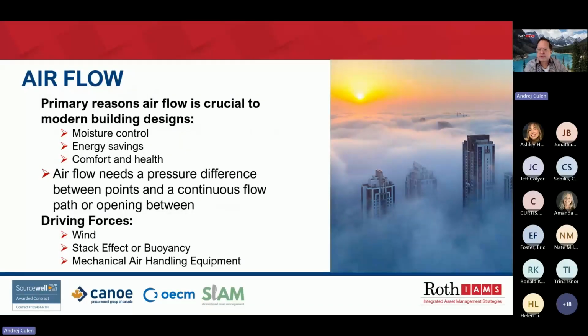The control of airflow is a crucial and intrinsic part of heat and moisture control in building enclosures. A large fraction of a modern well-insulated building's space conditioning energy load is due to uncontrolled air leakage. Wintertime condensation of water vapor in exfiltration air or summertime condensation of infiltration air within assemblies is one of the two major sources of moisture in the above-grade envelope system. Driving rain is the other.